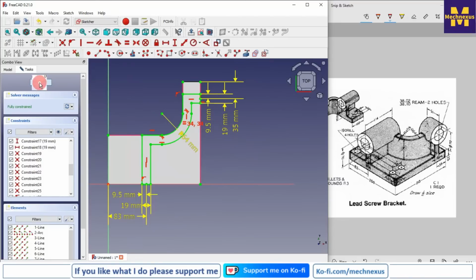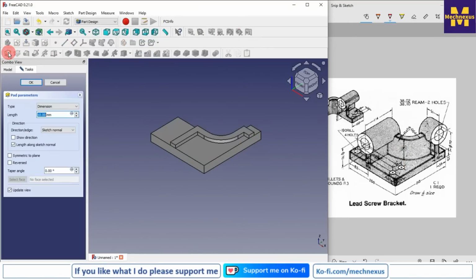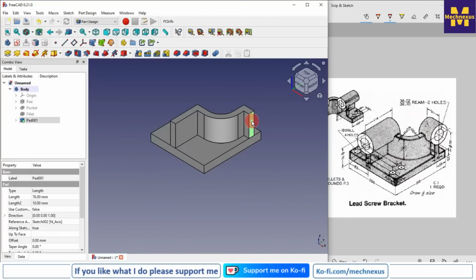Now I will close it, and total height is a 76. So I will click on the pad and I will give the height 76, and now we will create the 2 cuts of the maximum diameter which we have. So for this, first we will select this one and create a sketch.